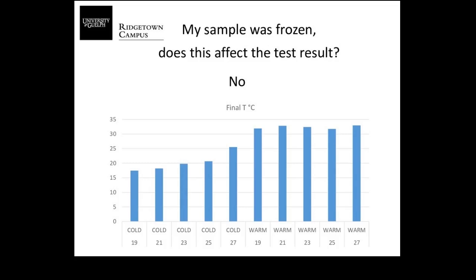And we processed that grain as they would in the control house. The processing of the grain, the splitting and the grinding and so on, and preparing that sample, warms that sample up to within a good range. And so the driest grain, with the least amount of moisture, ended up being about 17 degrees before testing, and that falls well within the range of doing a good test.